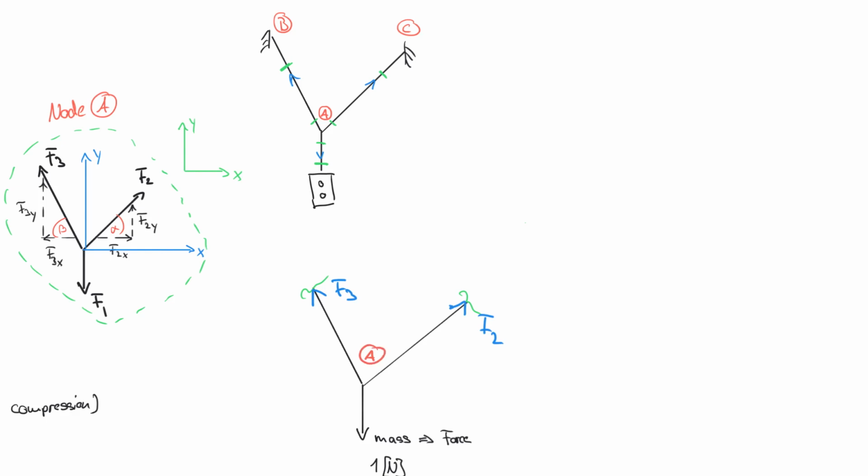And the reason I'm repeating myself here over and over again and explaining this one more time in a free body diagram, the real world, and then developing the free body diagram, is because this concept here, where I cut it first and then I bring in the forces, is so important, because that is the trick that engineers always use. So engineers really always check, like, what happens if I remove the force that holds it in place.